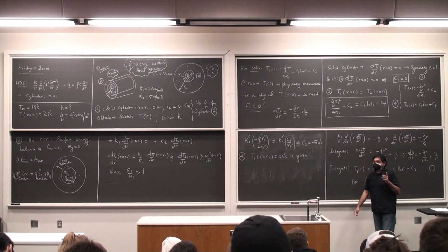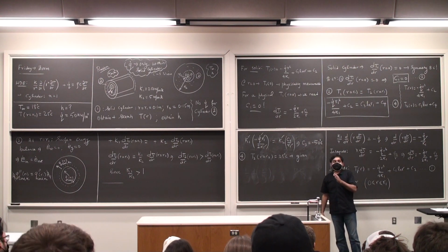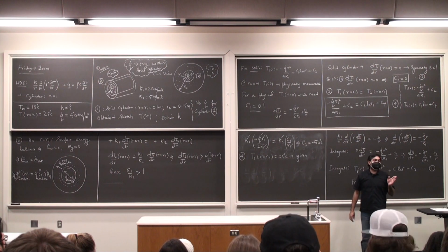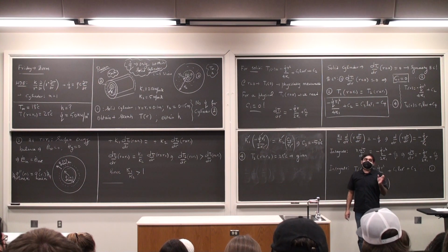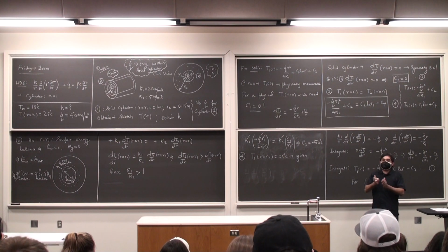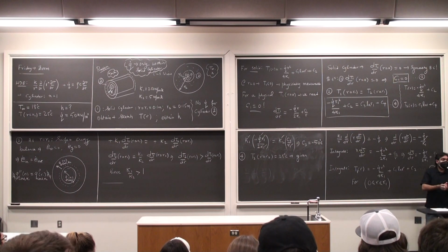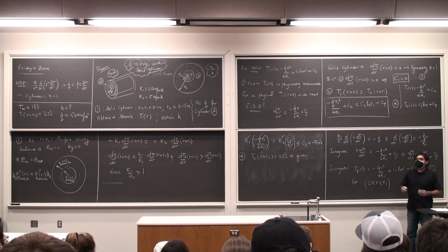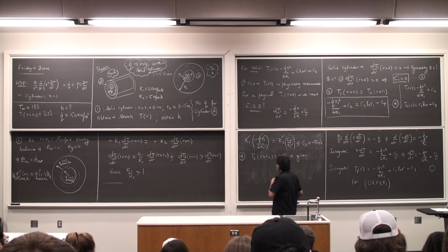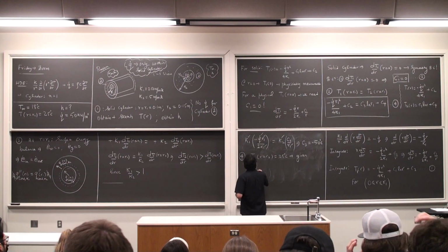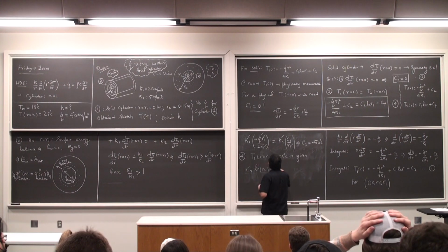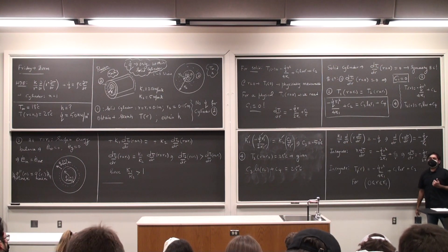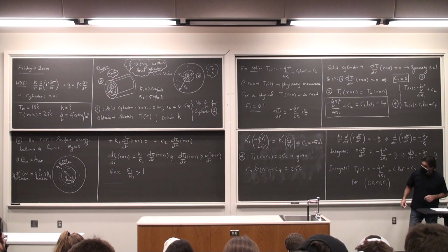Notice, if I don't have radiation, it does not matter what units I use for the temperature. I can solve the problem in Kelvin or I can solve it in degrees Celsius. If radiation becomes a factor, I cannot do that because of the nonlinearity of the temperature difference between the surrounding and the surface. So in this problem I can just deal with Celsius. Don't need to convert everything. So substitute. C3 logarithm of R2 plus C4 is 25 degrees Celsius. R2 is known, 0.15 meters. Substitute. Solve for C4.